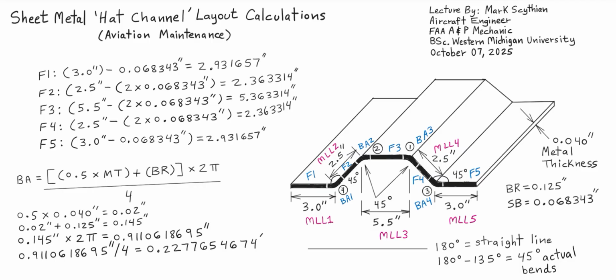So again, where do we truncate around? We can use the tolerance plus or minus 1/32 inch, the FAA sheet metal structural tolerance of 1/32 inch, which is also 0.03125 plus or minus.